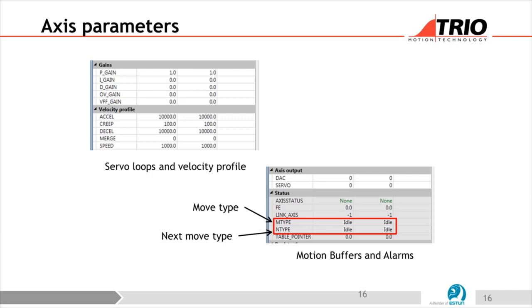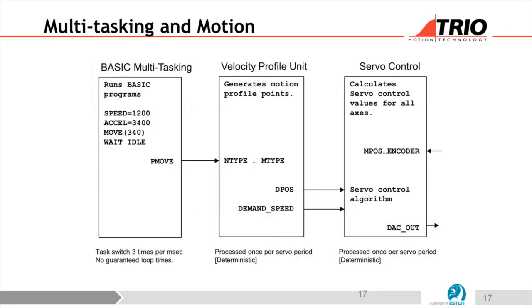And once it's in there, it's using the preset parameters that you've put in there, which we've already been setting up, some gains, for example. So the motion part runs really on its own, completely, almost like it's a separate device in some ways. So when your program comes down and does a move, so you come down here, set the speed, actual, do a move there, that move initially goes into the program's own buffer, and in there it is then signalled to the motion system to say, hey, I've got a move for you. And then the motion system will go, okay, I'm free, that axis is not doing anything, give me the move.